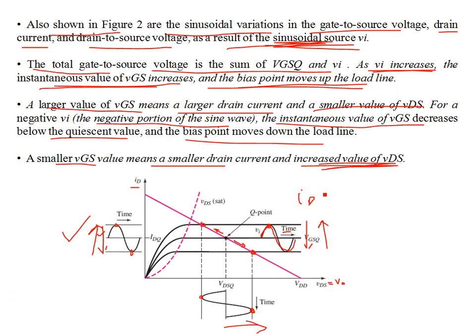In order for this MOSFET to operate as a linear amplifier, the drain current has to be the saturated drain current. It has to be in saturation, independent of VDS. As we talked about earlier, the relationship in the saturation region is given by VGS minus V threshold, that's the overdrive voltage, whole square. So basically, this ID has a quadratic relationship with VGS, which has two components.